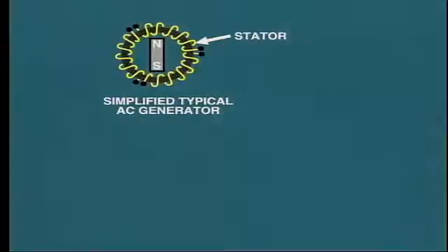We have been moving the coil with the magnet in a fixed location. This is basically what's done in the brushless exciter, which provides the excitation voltage or rotor voltage for some AC generators. Now, this will be discussed in segment E of this module. However, this is not a practical arrangement for large AC generators, as huge slip rings would be required to accept the large AC generator output current from the rotor. Instead, the magnet is rotated while the coil remains fixed to produce an AC voltage.